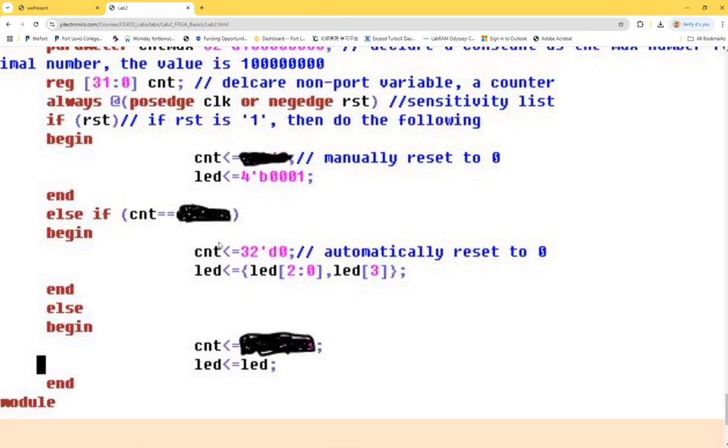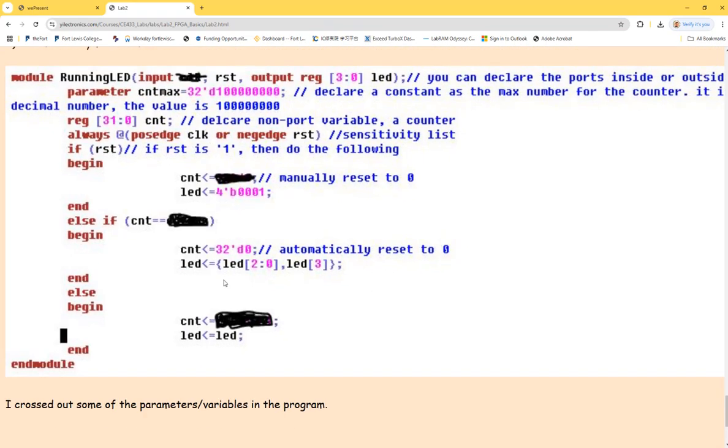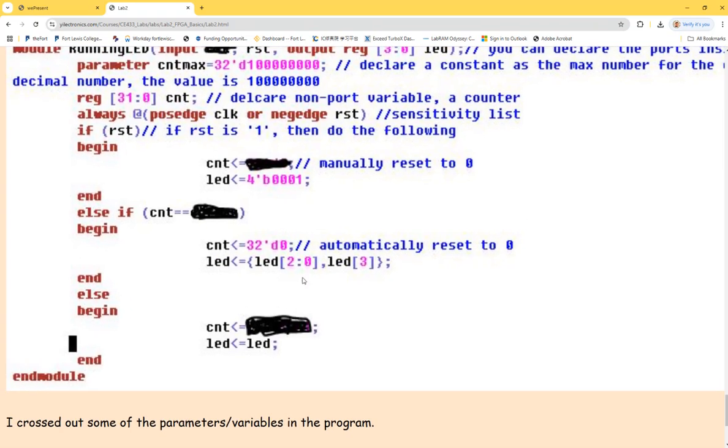One very quick question. Am I shifting the testbench keywords, or am I just shifting something else in here? By shifting the LEDs, right? Remember I told you guys in the constraint file, the LEDs are keywords and it's case sensitive. So it has to be lowercase LEDs, right? So am I shifting the real LED keywords of the FPGA or not?